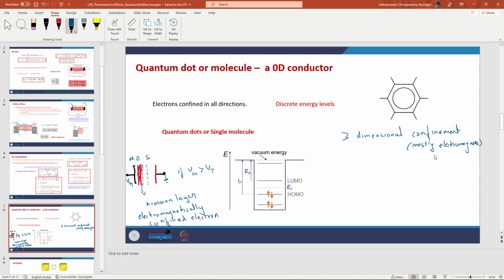Most likely not. Even the quantum dot devices that use electromagnetic confinement, maybe they cannot be manufactured on ICs because there are way too many electrodes and way too many controlling voltages. So when we talk about packing multiple such devices, there might be crosstalk between voltages, and maintaining the confinement may be difficult.